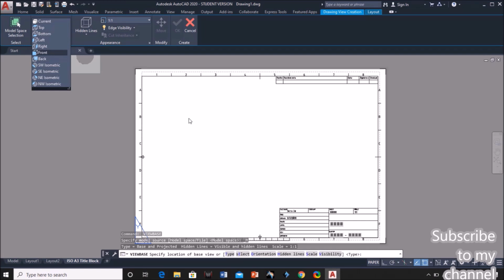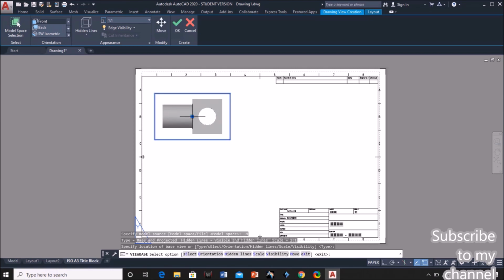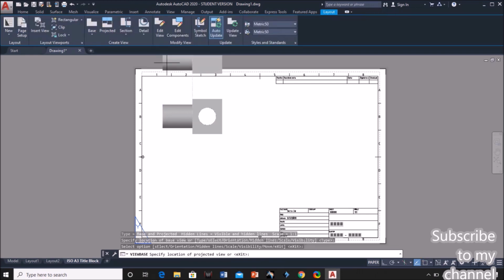Coming to first angle, first you will get the front view, and beside it you will get the side view, and down you will get the top view. So like that we need to keep the views. First we're going for the front view. So the front view of the object is like this. After keeping the position of the front view, just click on OK. So automatically it will be projected to the other views. So this is the top view and this is the side view.